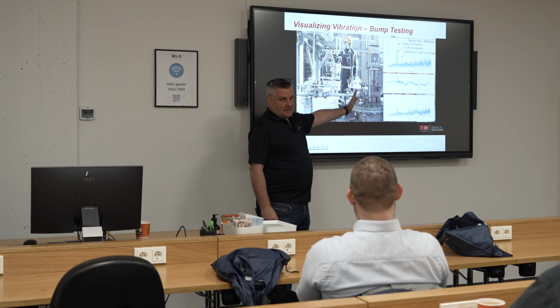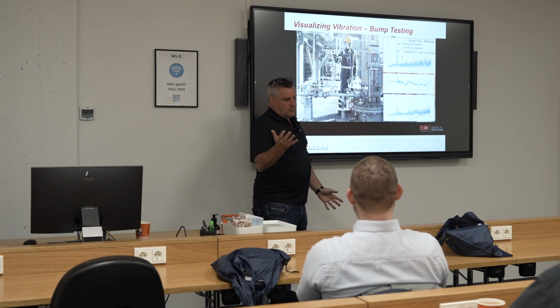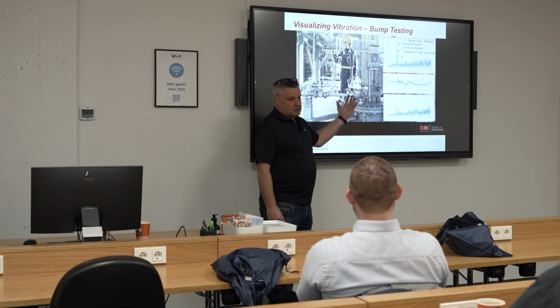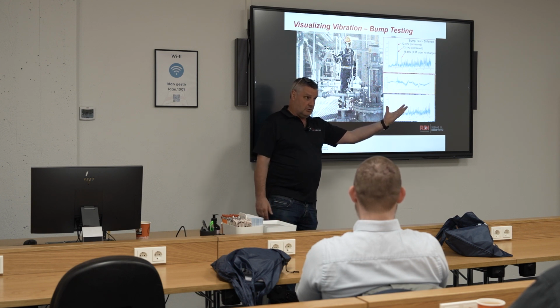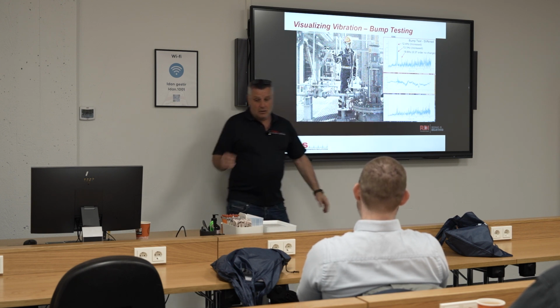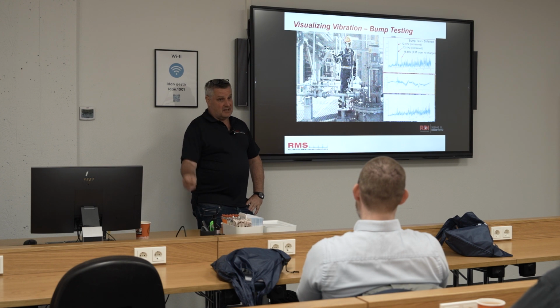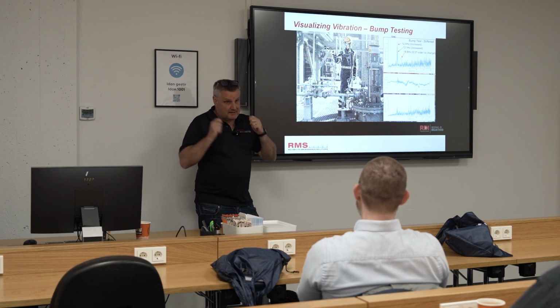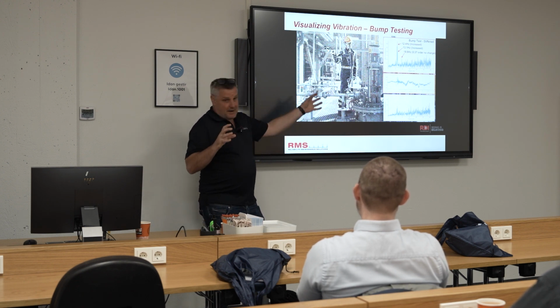It has to be static. But with another bump test, with an instrument, like you have, I don't know if it'll do it, but it may do it. There's an option in the software called negative averaging, which, when I'm impacting it, will take away the background noise.